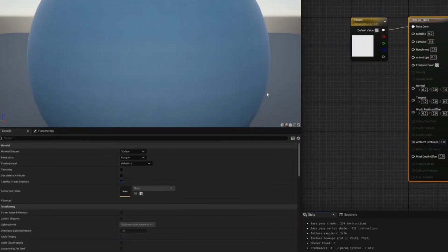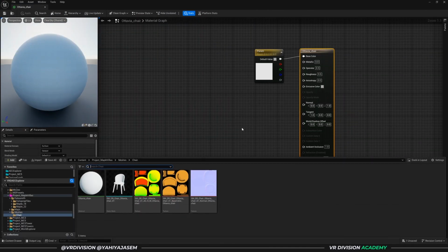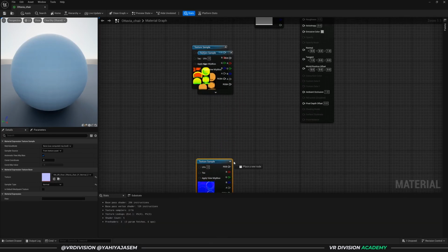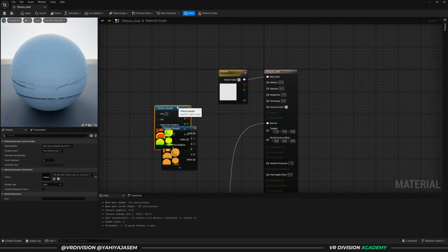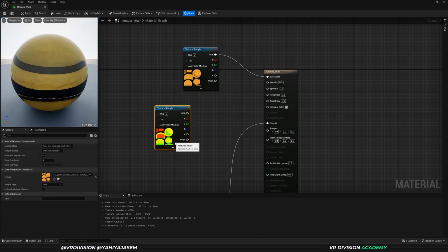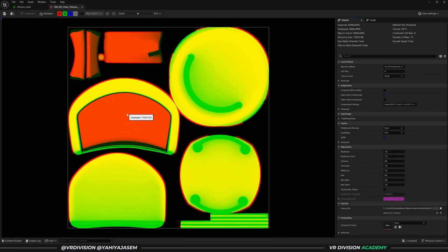But now let's double click this. And all we need to do is press Ctrl space, select our three textures, click and drag and place them here. So we want to connect the normal to normal. We want to connect the color to base color. And this funny map, the RGB map, is a texture with multiple textures baked in it.